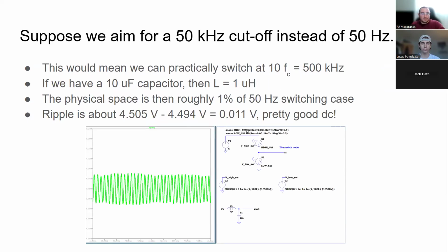And so we're going to try to shoot for 50 kilohertz. I was looking around at what's available. These switching regulators actually come in integrated circuits as well, just like the linear regulator. And 500 kilohertz is a typical switching frequency for a lot of them. So that's where this 50 kilohertz came out of. I didn't just pull that out of nowhere. So this would be a tenth of our 500 kilohertz switching frequency.